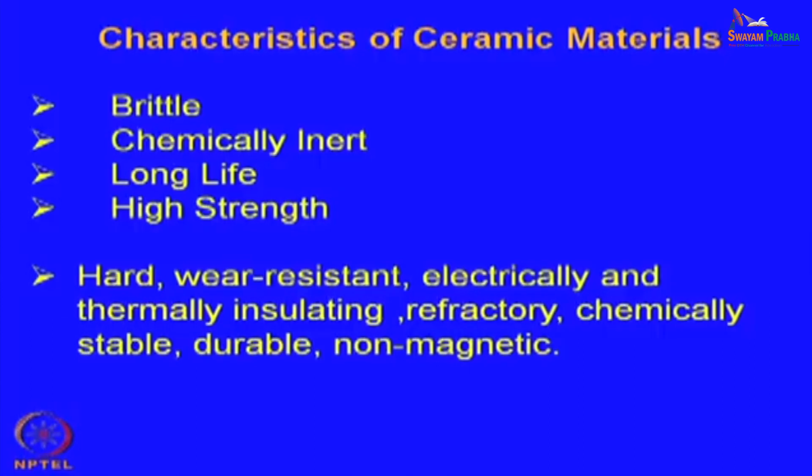Normally, they are electrically as well as thermally insulating, that means the electrical conductivity is very poor, as also the thermal conductivity. Refractory nature means it is basically high temperature resistance. As per definition, ceramics are high melting materials and require high temperature for their processing, and therefore, they are the most common candidate material to be used as a refractory material for lining of furnaces, particularly where a very high temperature has to be withstood.